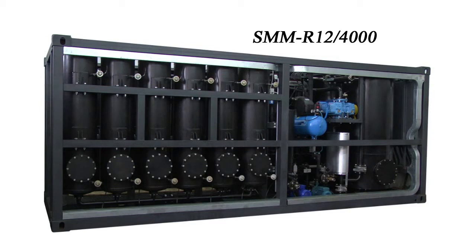After regeneration, the oil goes to a filter for final purification from solid impurities and filtration of oil. After sorbent saturation by the products of oil decomposition, the system switches to sorbent reactivation mode. The sorbent is reactivated by igniting it and creating a strong airflow over it. Heating causes the sorbent to ignite, which purifies sorbent pores. Reactivation waste products are accumulated in a special collector vessel for draining.